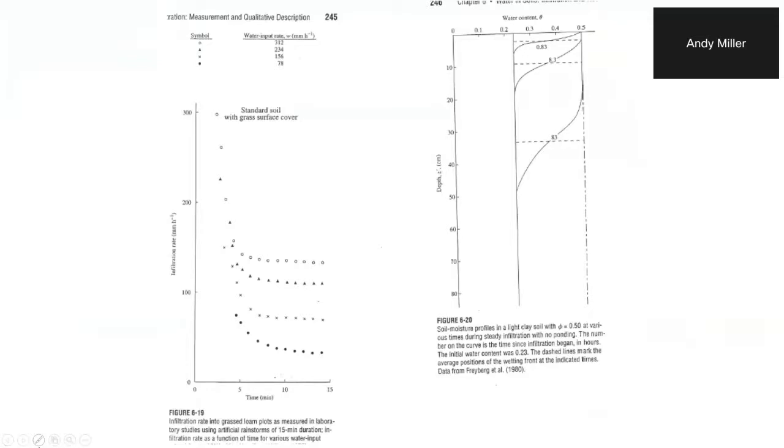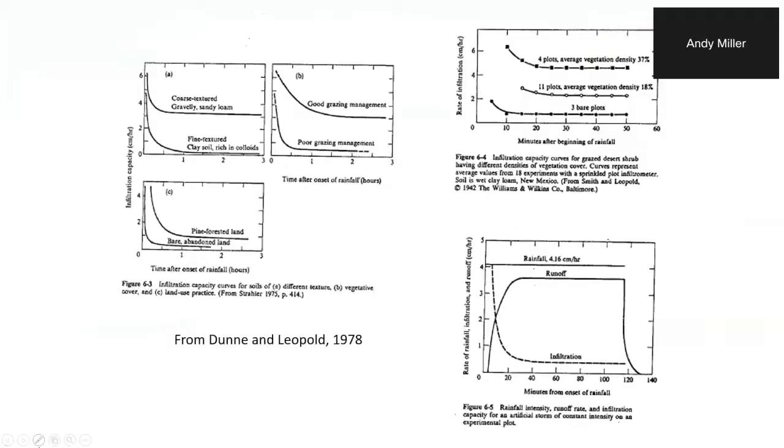You see it's even more spread out, but it's also moving downward. And then after 83 hours, it's moved farther downward, and it's also more dispersed over a broader range of depths. So that suggests that the wetting front actually is going to tend to broaden and not necessarily be a straight flat surface. And yet I'll show you other findings that suggest that you could still get away with assuming it's a flat surface and make reasonably good predictions.